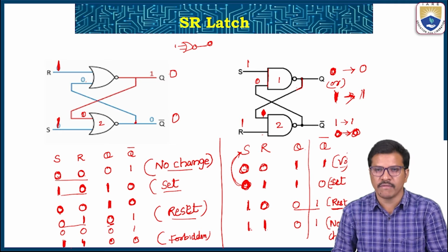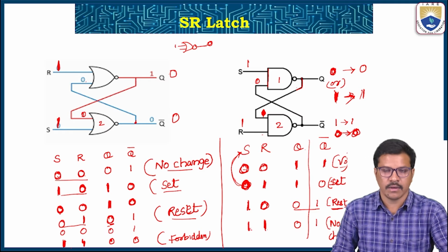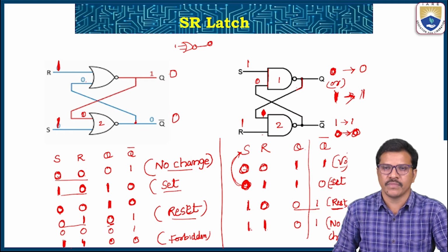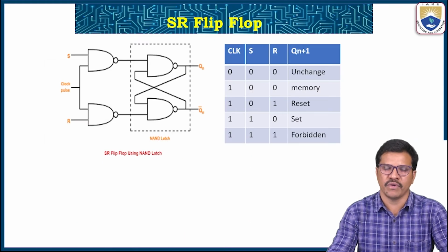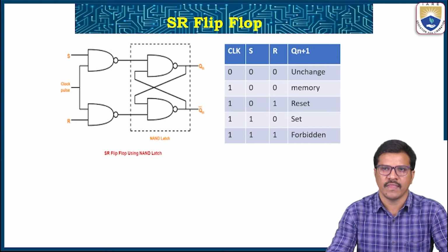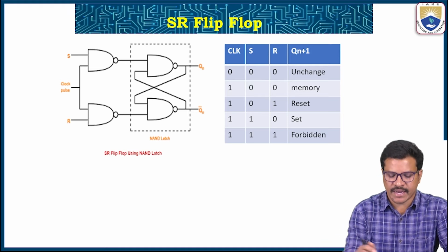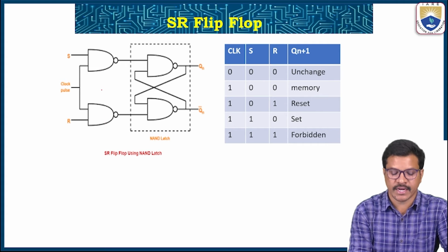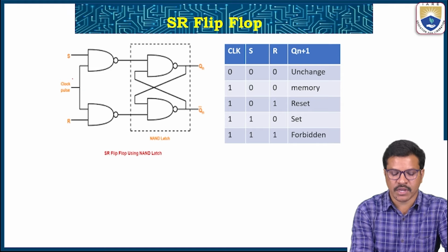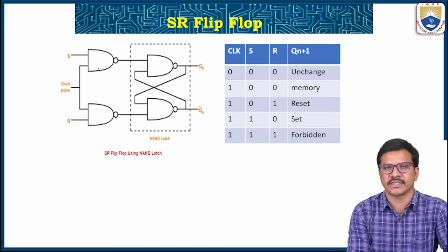Okay, let us move to the flip flop. So remember these two tables, then we can use them to understand the flip flops. Now coming to the flip flop. A flip flop is a sequential circuit which can store binary information of logic 0 or 1, by just adding gated circuits like two NAND gates connected with the same S and R, and connected with a common clock pulse.